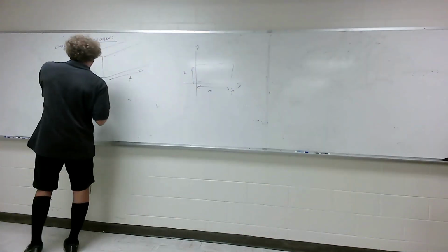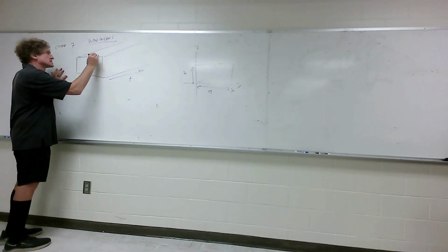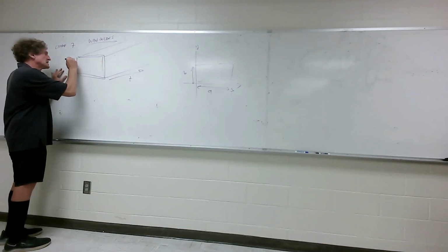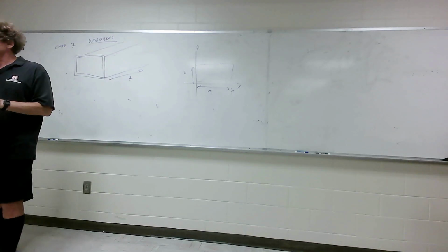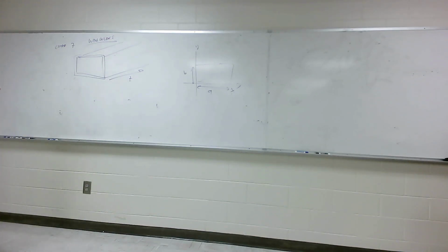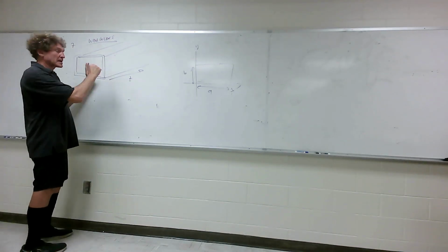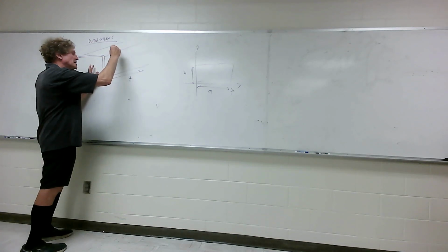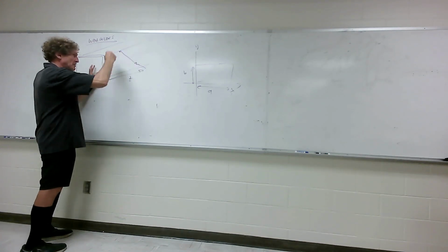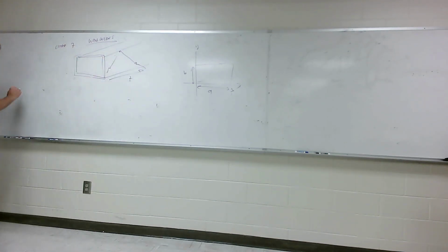Now the thickness of the walls on these guides is many skin depths, so you don't worry about skin depth effect with a waveguide. What happens in a waveguide is it causes the wave, either TE or TM, to bounce up and down. If you're looking at the side, the wave is bouncing like this, which means, if it's air-filled, the group velocity of energy flow is always less than the speed of light.